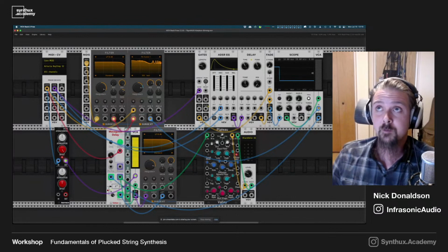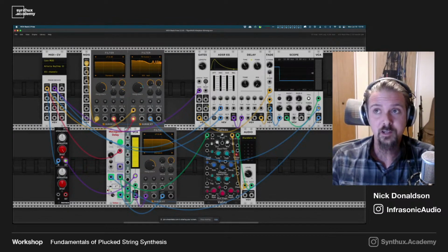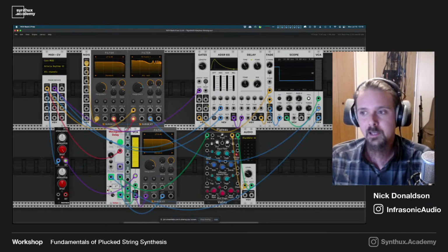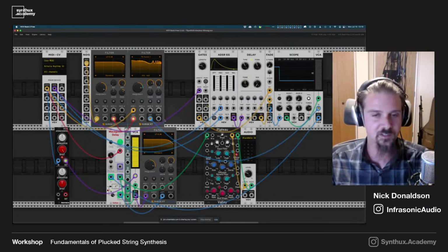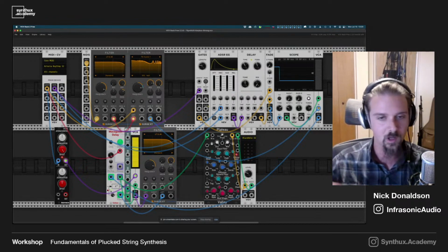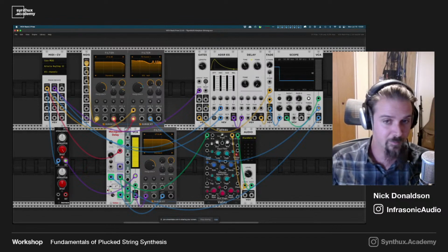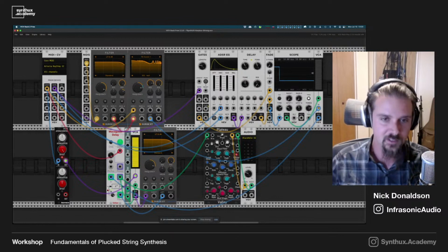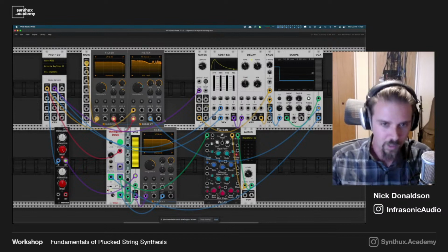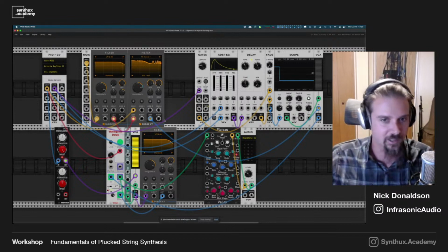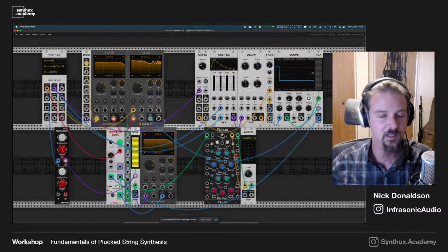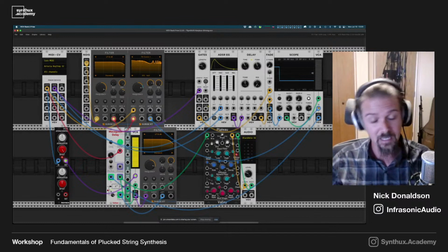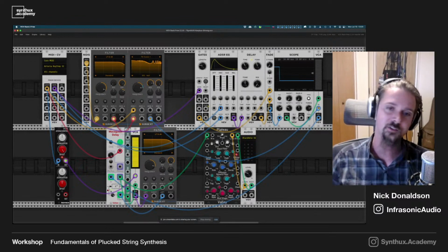Yeah, there are several examples that go beyond this. Karplus-Strong is a very simplified version of the general realm of waveguide physical modeling. So anything that's energy resonating in a physical system of a certain length with certain reflections along that length. That could be everything from hitting a metal plate to a drum head. Drum heads tend to be very inharmonic, but still have very similar underlying physical principles. It's a waveguide of a tense membrane that's vibrating and reflecting off the edges in really complex ways. Hitting a tube. So Mutable Instruments Rings is the classic, and Elements, of course, takes it a little further with all sorts of excitation modes.